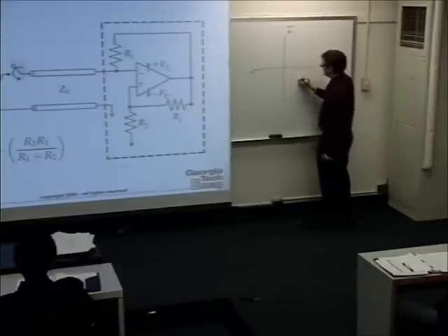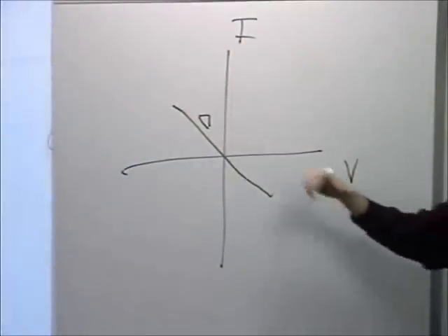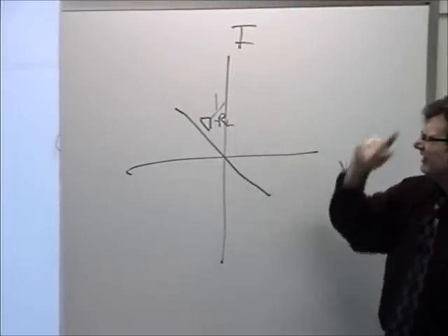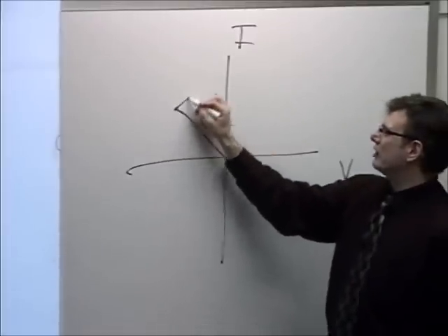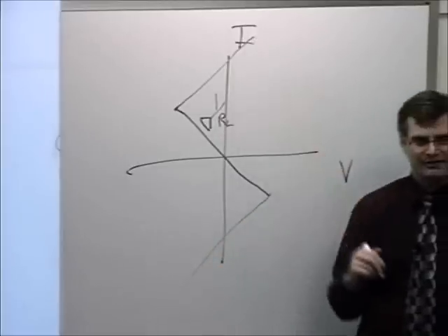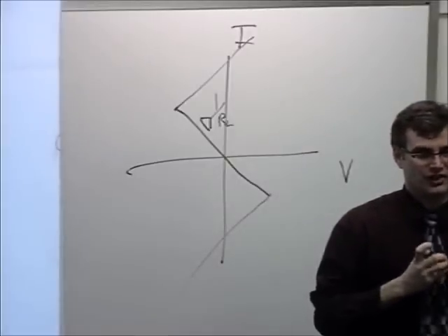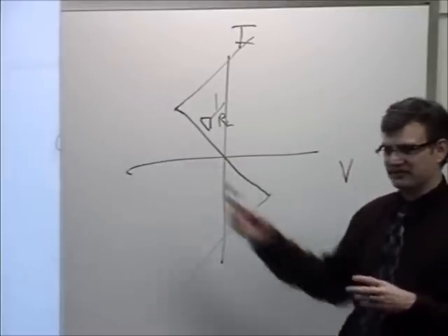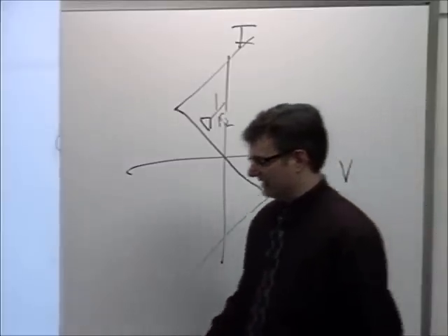this looks like a negative resistor up into a point. The slope of this, rise over run, current over voltage, will be 1 over that negative value that we calculated there, RL, 1 over RL, which is negative. I don't need to put a negative sign there. And then once it saturates, it'll kind of go back to having positive resistance characteristics. So it's piecewise linear, but very, very nonlinear in its entirety. Very bizarre circuit element. And you could iterate this thing with this in the network as well. You'd have to come up with some weird piecewise functional linear dependence. But you could iterate this and solve this.